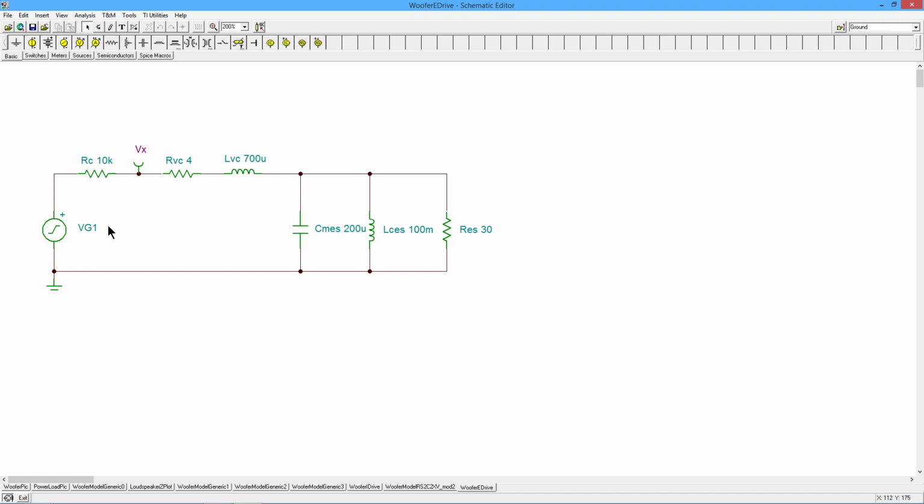Ideally, you want a sine wave generator over here that can get you maybe 10 volts peak, okay, good size signal. And the resistor you're going to need should be at least an order of magnitude, preferably 2, larger than the biggest value you're going to get out of here. So I'm going to say at a minimum 1k ohm, 10K would be better. So this combo right here, the voltage source and the resistor, basically behaves as a current source. So you feed that current in, and again, this is your loudspeaker, and you just start taking measurements.